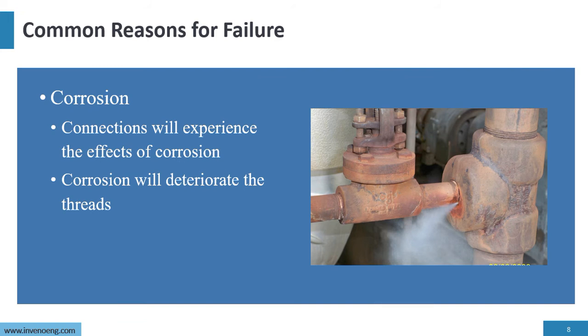However, we have oxygen corrosion in the system, and this is coming from the boiler plant operation. So for thread failures or any connection failure, including corrosion failure, we need to look and determine the type of failure. Don't necessarily blame CO2 corrosion for the leak point.